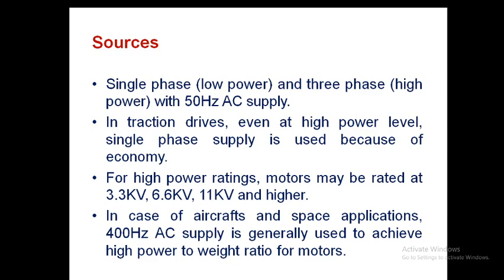Traction drives generally require high power, and even at high power levels, a single phase AC supply is used. Generally single phase is used for low power applications, but because of economic aspects, in traction drives also single phase AC supply is used.